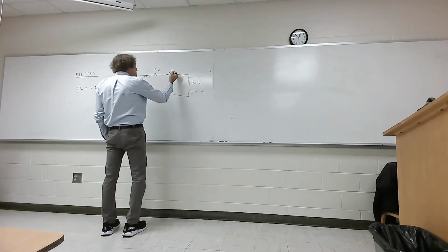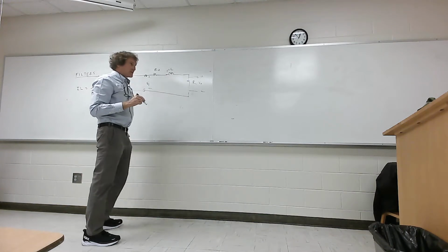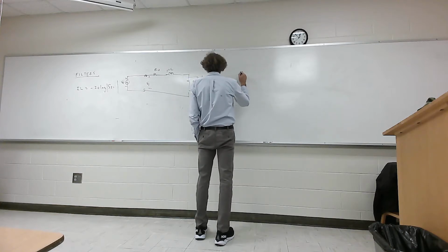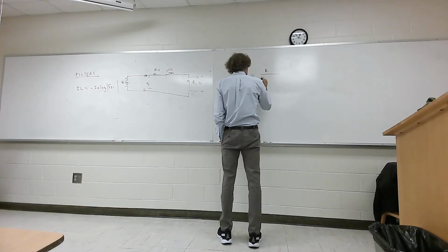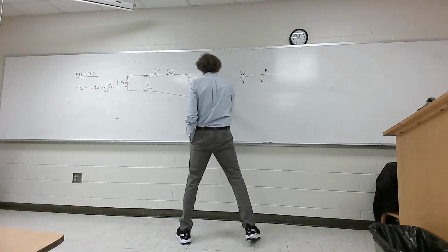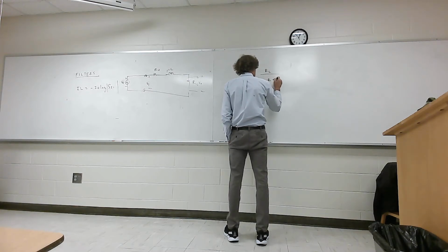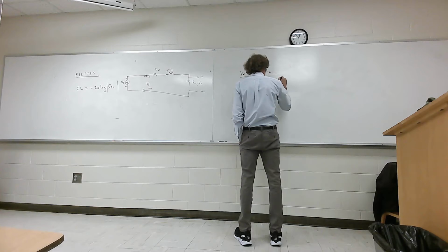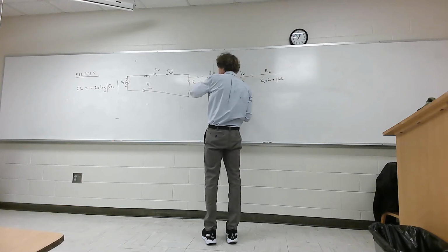Here, the inductor would have an impedance of j omega L. If you wanted to write the basic V out over V in, that would be R load over R load plus R naught plus j omega L. If you're thinking about connecting to transmission lines, this is V2 minus over V1 plus.